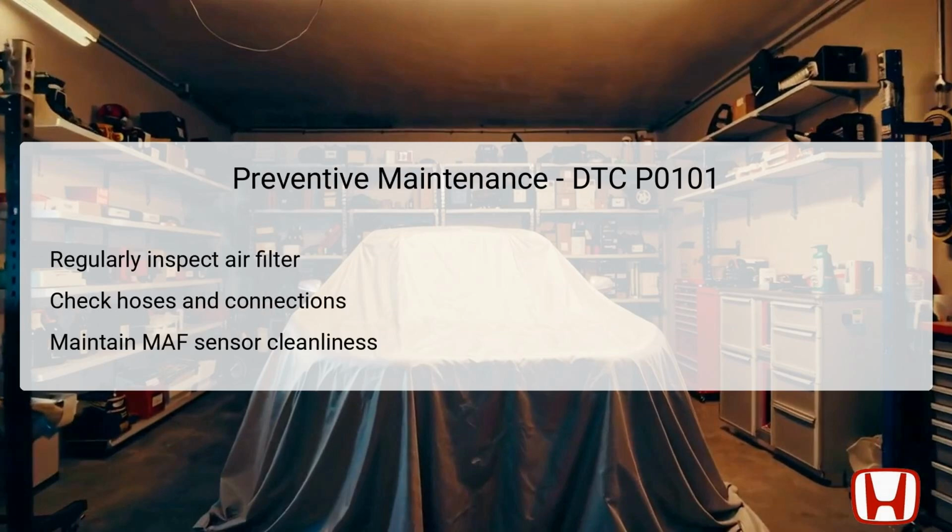To prevent future occurrences of DTC P0101, regular preventive maintenance is highly recommended. Start by routinely inspecting the air filter. It's vital to maintain airflow and optimize engine performance. A clean air filter promotes optimal function of the MAF sensor and overall vehicle efficiency.